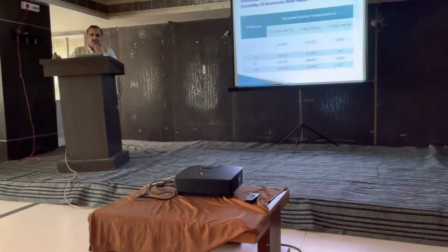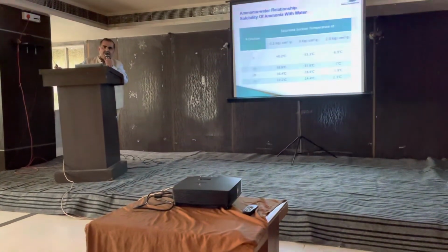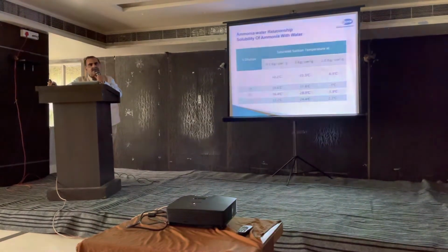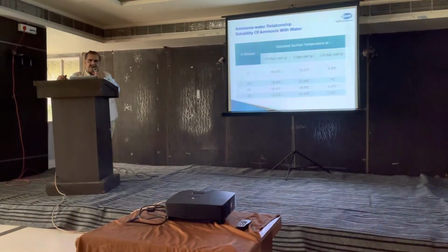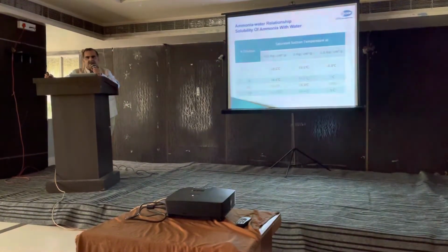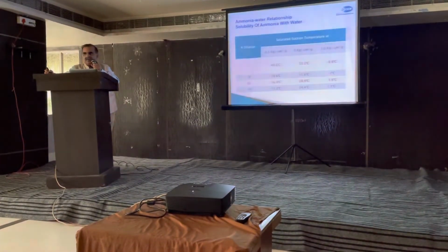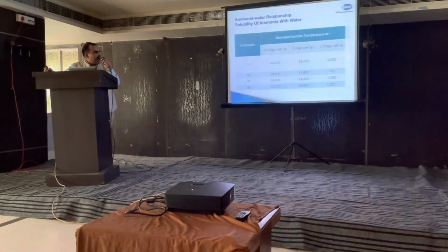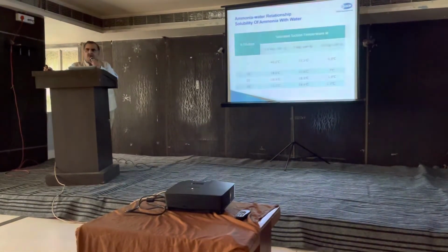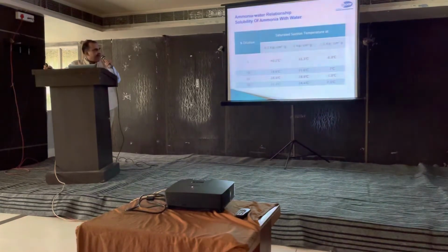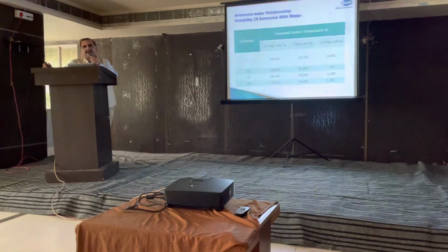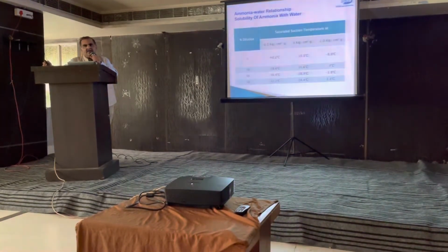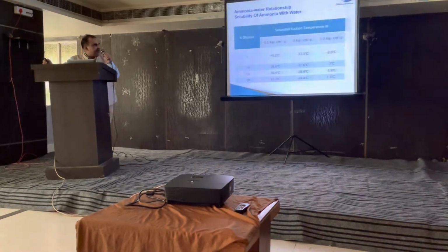Now, as Nikhil has told us about energy efficiency, COP is directly linked to the suction pressure and the discharge pressure of the compressor. So if I am reducing my suction pressure, naturally my COP is going to suffer, the energy efficiency of the compressor is going to suffer, and because the compressor is now doing more work, the overall refrigeration capacity of the plant is going to decrease. It means I will not get the same refrigeration effect or capacity from the plant at the rated conditions.